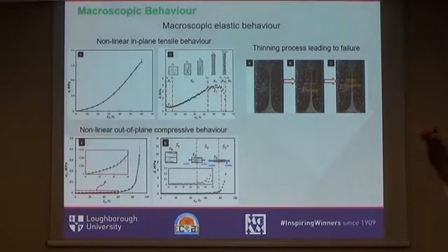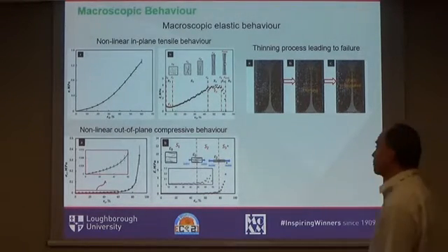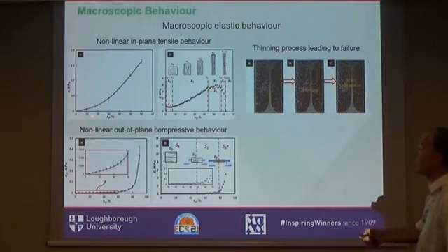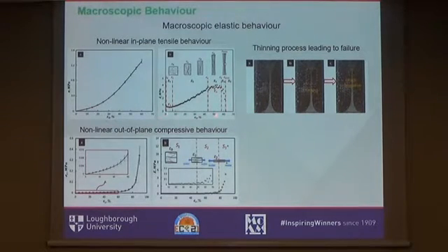That's why generally when you are loading it, stretching it as was shown here, first of all the segments between the intersections reorient themselves in the direction of the stretching. Because of this, we have this non-linear type of behavior, and depending on the amount of stretching and the microstructure, we have different types of instantaneous Young's modulus. You can see here it's constant, then linearly increasing, then constant at a higher level, then decreasing, and then it is zero when it has failed.